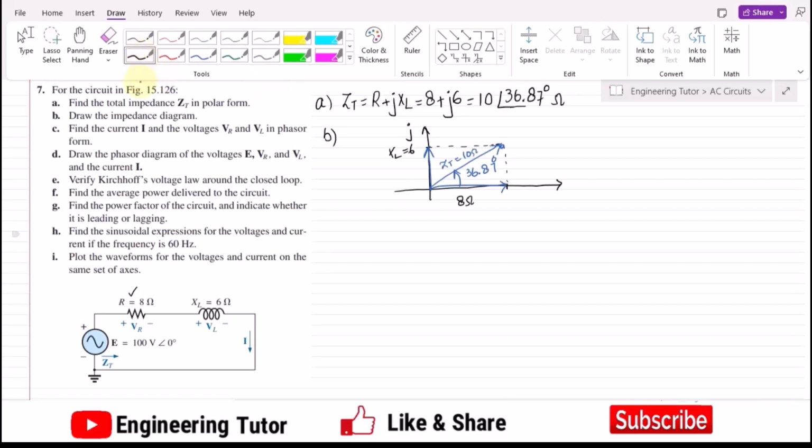Now in part C, find the current I and the voltages VR, VL in phasor form. So in part C, I have to find the value of current. I have also found the total impedance, so finding the total current here is very easy. It will be E divided by Z of t. The value of E is known, and that is 100 volts with the angle of 0 degrees.